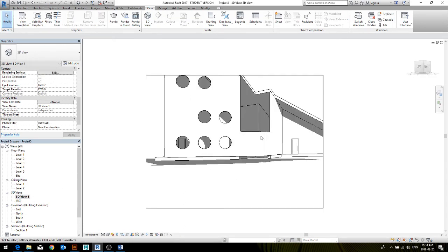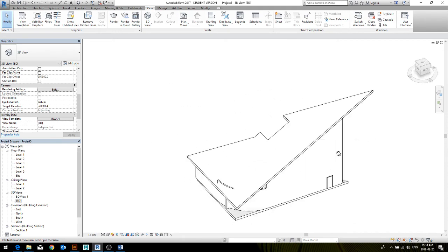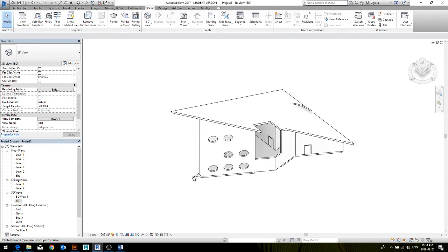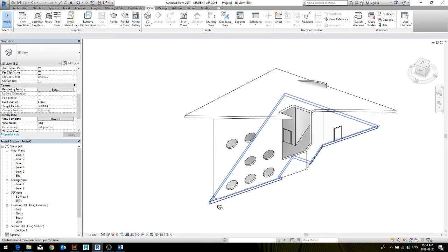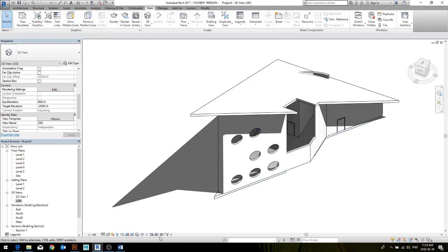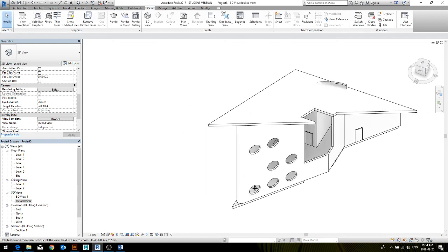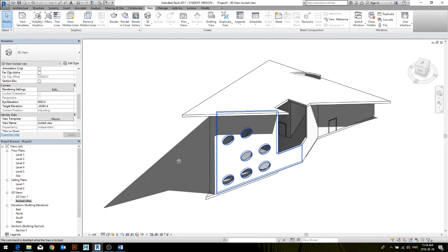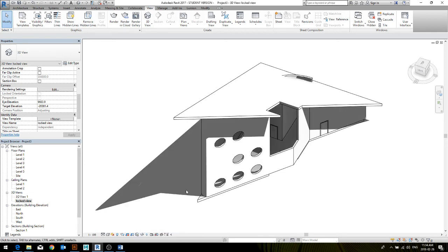Another thing that is good to know in a 3D view is that if you have set a camera or a 3D view, and anybody who goes in, including yourself, and rotates and orbits around, is messing with where your camera was set, and it's not something that you can trust and go back to because it's lost as soon as it's moved. But there's this tool down here that you can lock your view. So if I lock my 3D view using that, I need to give it a proper name, locked view. Now I can only pan around, but no orbiting is allowed because the view is locked. So I'm safe for using it next time. So if you have a view that you want to repeat using on your sheets and stuff, make sure you lock them. I will unlock this so that I can orbit around.